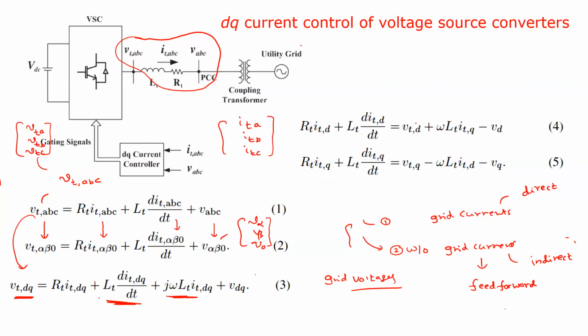From this, if you want this one only, this is the one. These two are the inverter voltages. So ultimately you require these two. Before that, we already discussed that there are two things: one is with grid control or grid currents, and one without grid currents. Now if you're using it without grid control or grid currents, these ITD and ITQ are the grid currents.